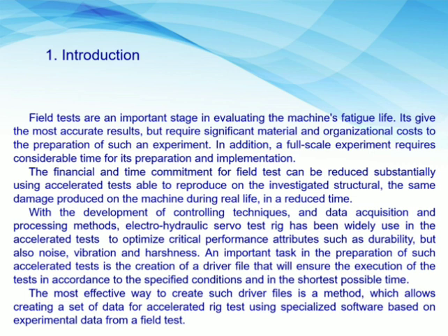With the development of controlling techniques and data acquisition and processing methods, the electrohydraulic servo test rig has been widely used in the accelerated test to optimize critical performance attributes such as durability, but also noise, vibration, and harshness. An important task is the preparation of such accelerated tests in the creation of a driver file that will ensure the execution of the tests in accordance with the specified conditions and in the shortest possible time.